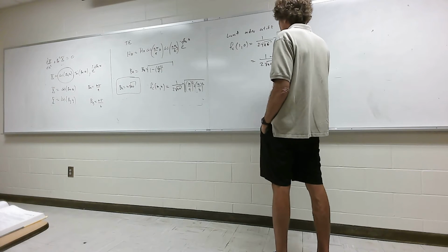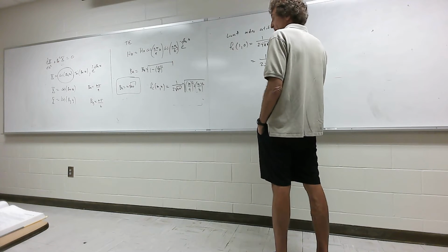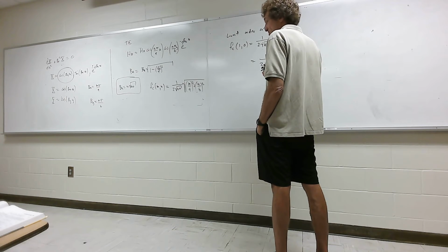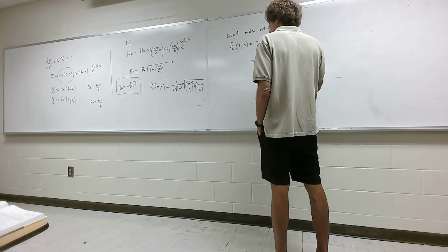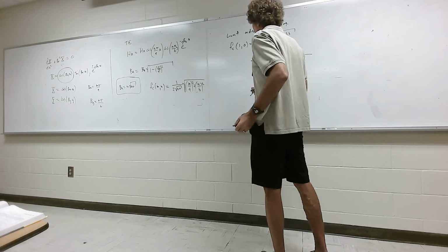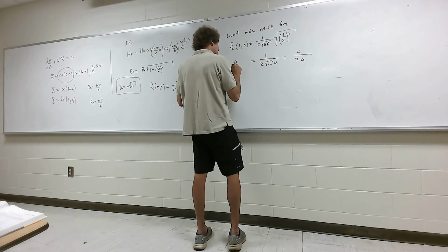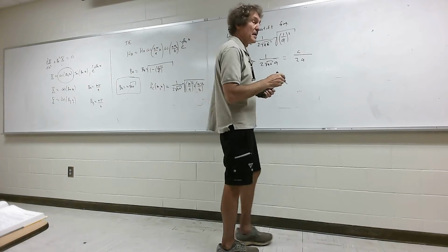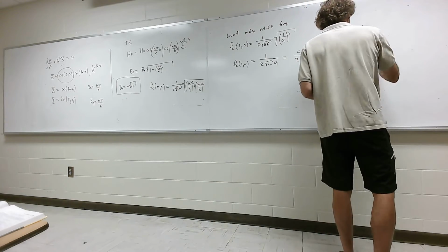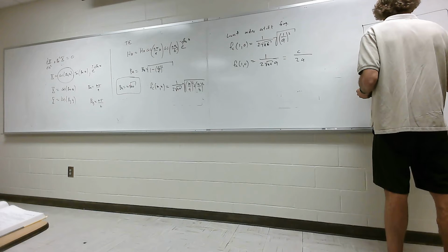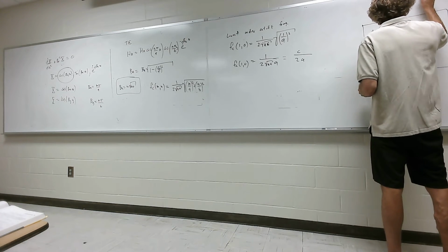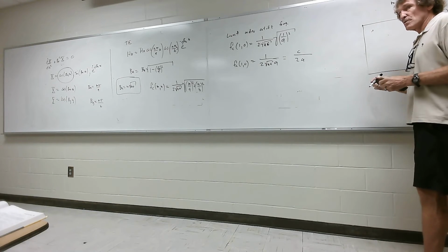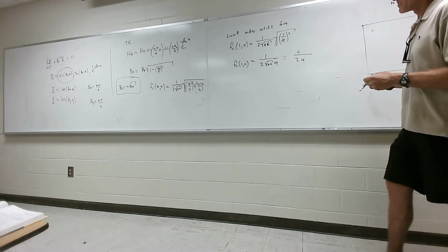All right, keep looking at that for a second. What is 1 over square root of mu epsilon? If it's mu naught epsilon, that's the speed of light. Really, this looks like the speed of light if we're assuming we have a wave in an air-filled guide, divided by 2a. Now, that's the cutoff frequency for the 1,0 mode. I want to show you something. When you have the 1,0 mode, and we take a look at the H field itself in here.